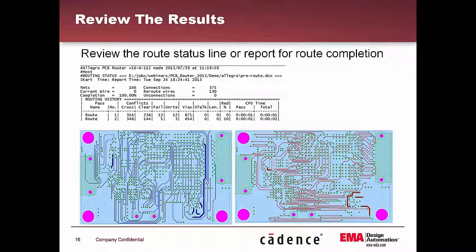You'll see that if you add additional routing layers, there's more horizontal and more vertical layer biasing, even more than what you see here. So I just wanted to preface it with that. So this is predominantly because I only gave it 2 routing layers. This is the route status report that you would see. So this tells me my completion rate, how many connections I have, and things like that, how many total nets in the design, and statistics about the board itself.